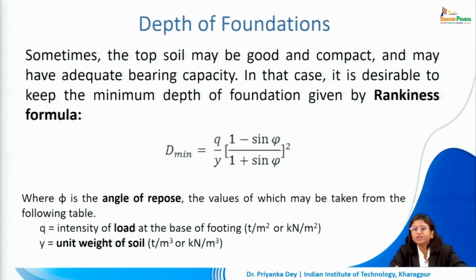So the depth of the foundation by the Rankine's formula, a quick recap again. So here we have d minimum is equal to q by y into 1 minus sine phi by 1 plus sine phi, where phi is the angle of repose. Now what is the angle of repose?